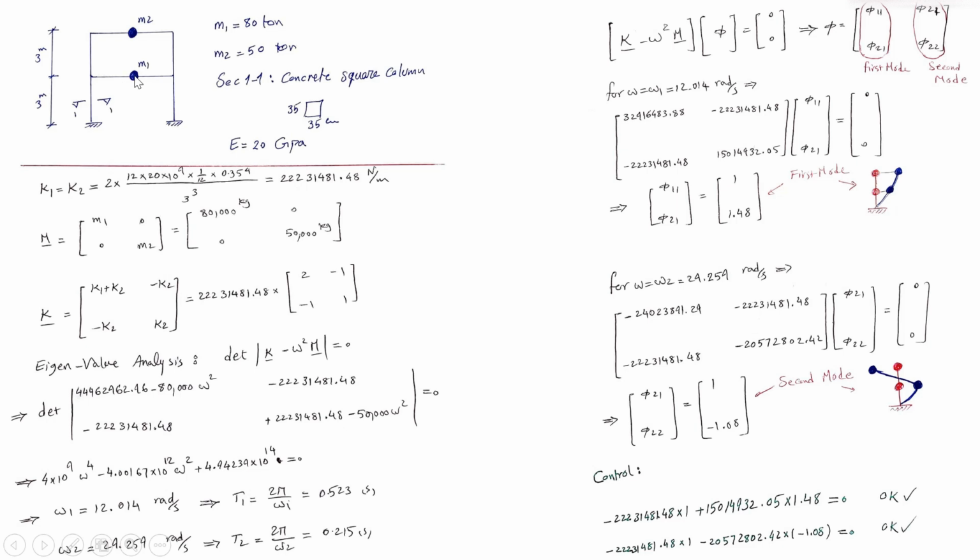The beams are rigid and the diaphragm is rigid, so it means that you can assume that this structure has only 2 degrees of freedom. We discussed this simplification during the past lectures, and if you accept this simplification, you can come up with this fact that the stiffness for each individual column can be calculated as 12 E I over L cubed.